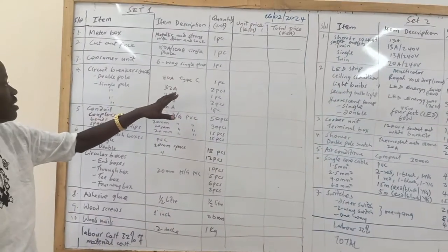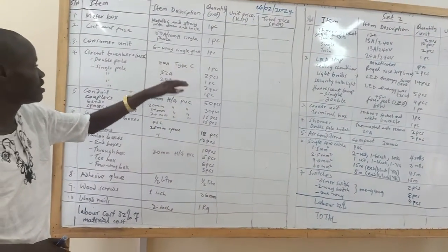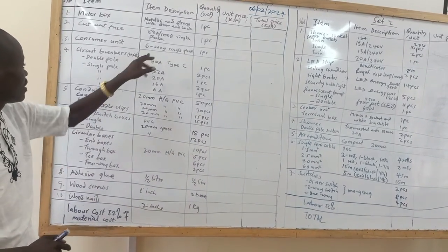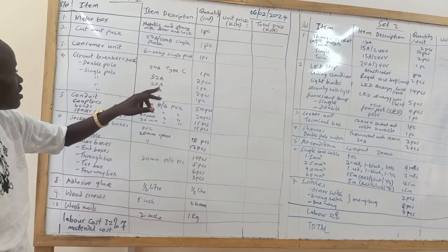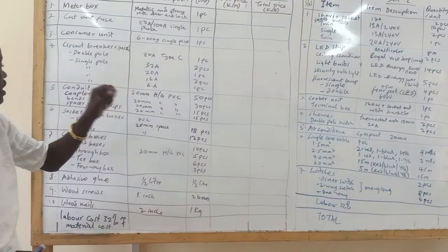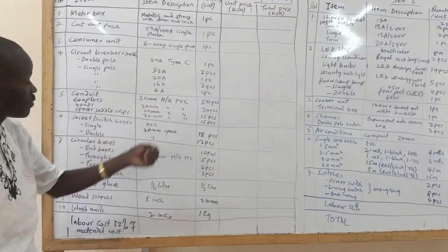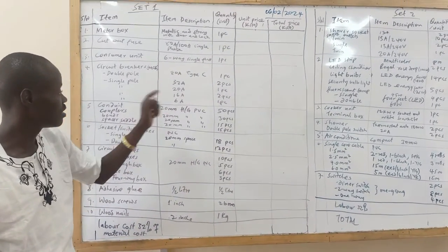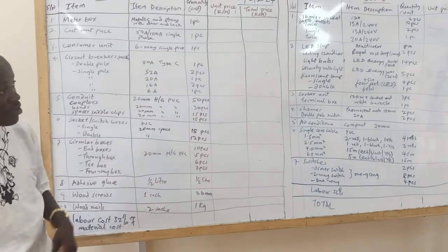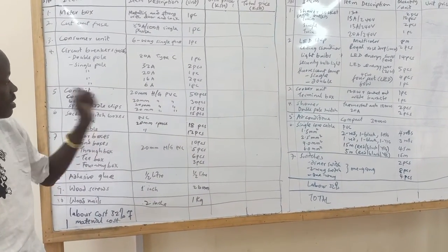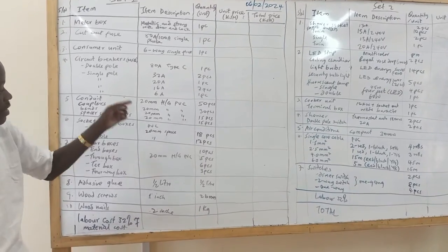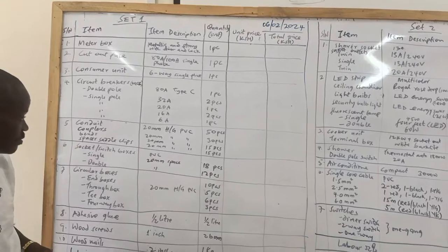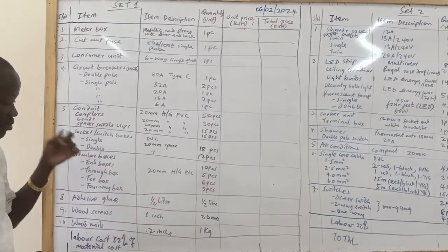So we realized that we needed 80 amp for the double pole main switch circuit breaker. And then we also needed 32 amperes, and not only one but 2 pieces, one for the cooker unit and the other one for the ring circuit. We needed 20 for the radio circuit, and then we needed 16 for the air conditioner, instant showers, and 6 amperes for the lighting system. So after doing the flow estimation from there, I was able to realize that I need